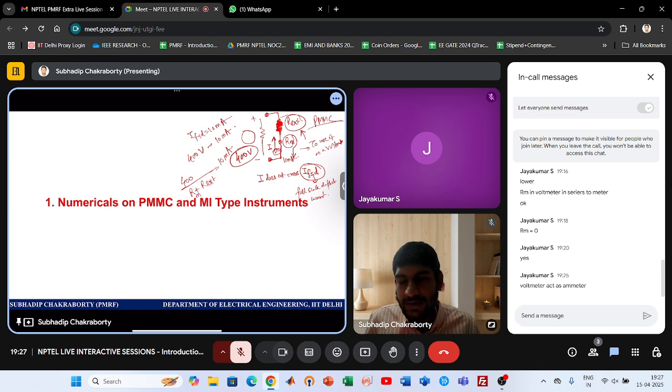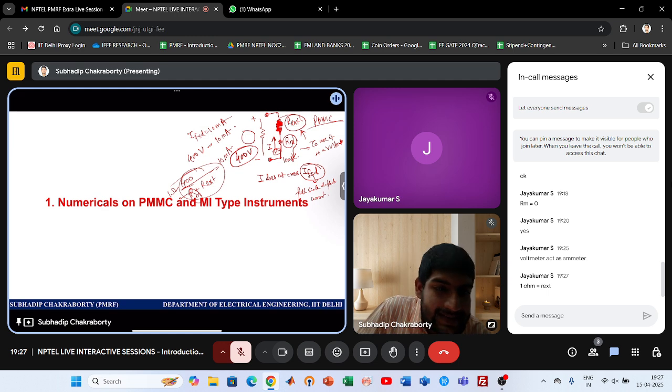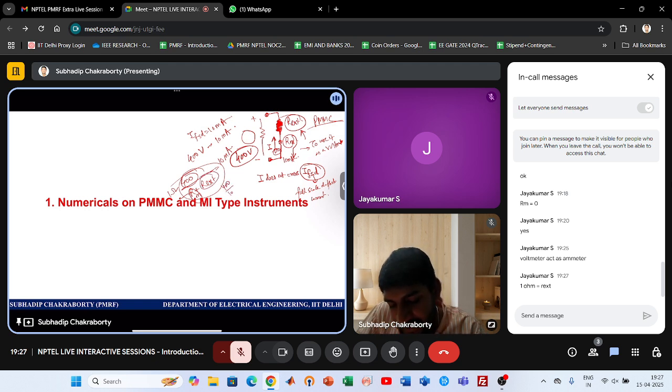That is the whole point. So for a voltage, you see this is the R_M, which is 1 ohm, but now the voltage has increased. Okay, so R external should be what? You plug it in the equation, 400 by 10 milli should be equal to 1 plus R external. So R external should be approximately equal to 40k minus 1, around 40k, right?